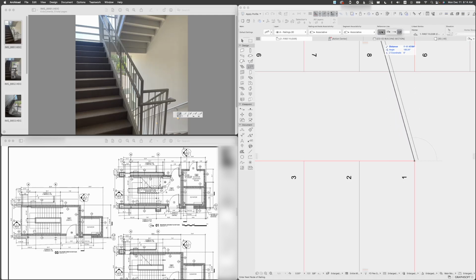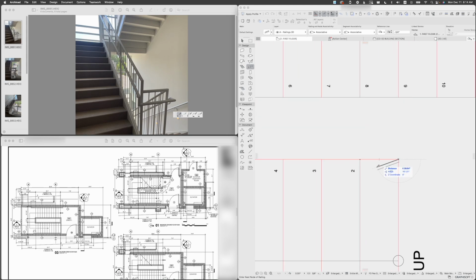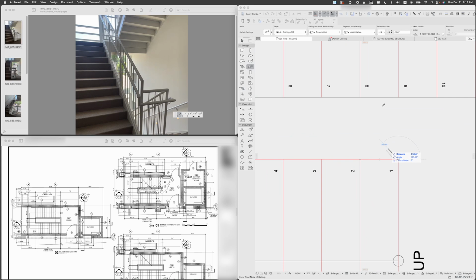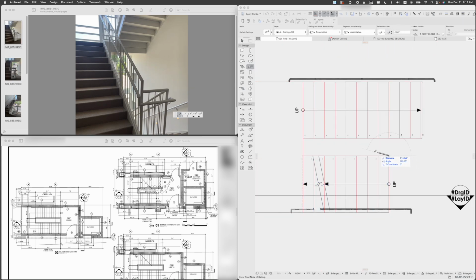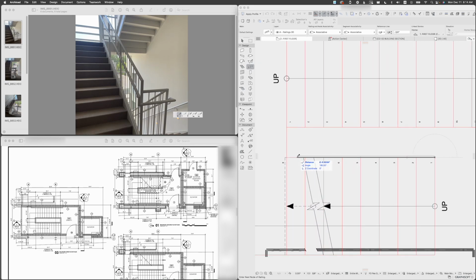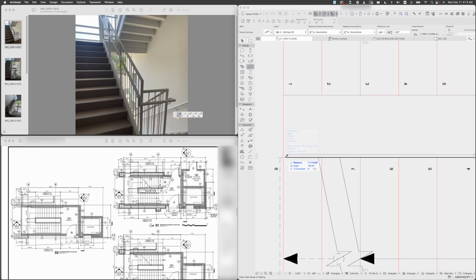I think if I click here and change the reference line, it will build the railing on the other side. But I think it's actually wrong. There's a stringer on the other side, so that was correct. We just don't see the stringer here, but that's another setting that we have to turn on. So I would extend the line, and it says enter next node of railing, and the next one will be right here. When I hover my cursor over, there's a little hammer icon, and the stairs is highlighted again, so it just means I'm doing it all correctly.